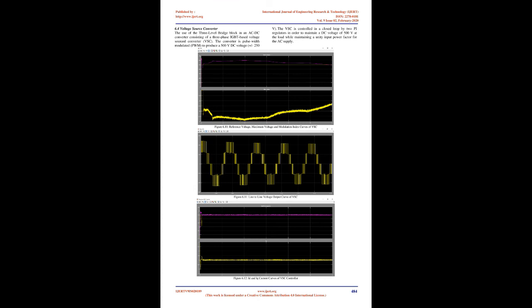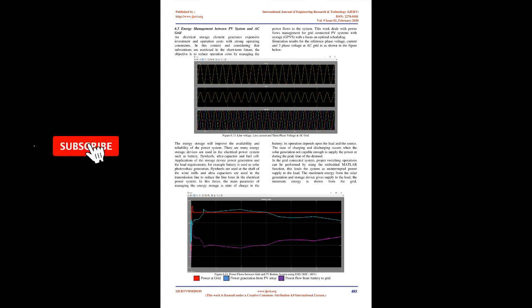The simulation results for the output voltage, output current, diode current and output generated power from the module are as follows. The output voltage from the PV module is typically around 500 V, and the output current, with respect to the load connected to it, varies in the range of 50A to 300A as per the input data conditions. The output power generated from the PV module is the product of voltage and current and ranges up to 1.5*10⁵ W. The diode current is the current drawn by the semiconductor diode and is inversely proportional to the output current from the PV module. Figure 6.6, output voltage, current, diode current and power curves for PV module.